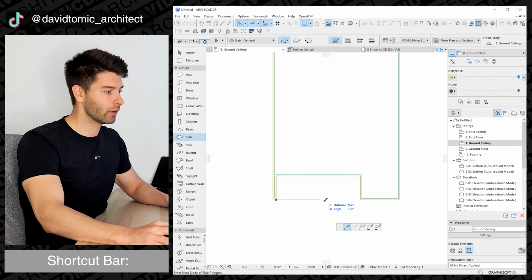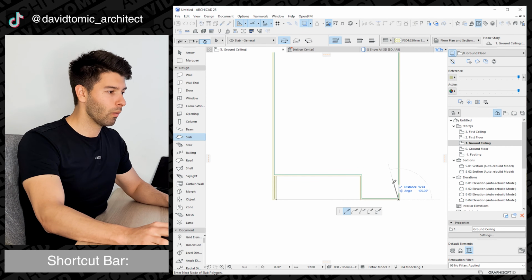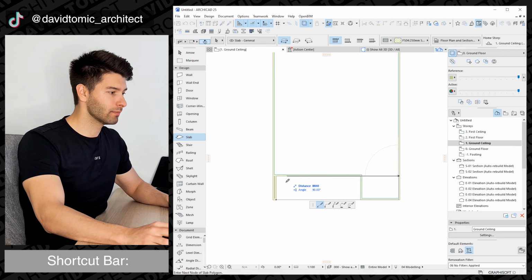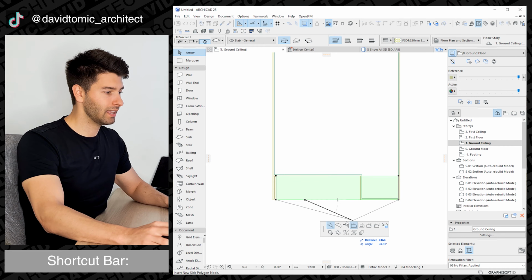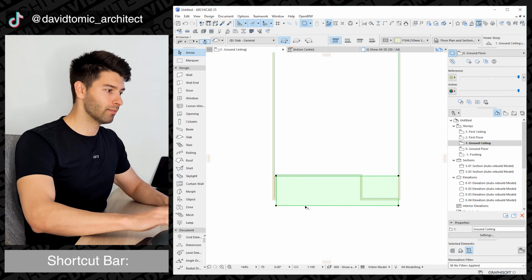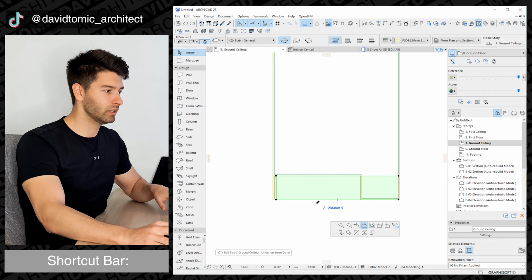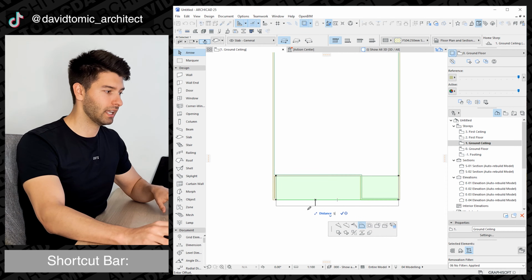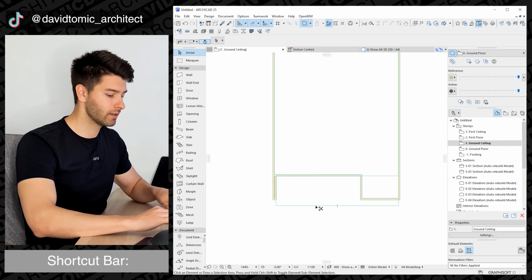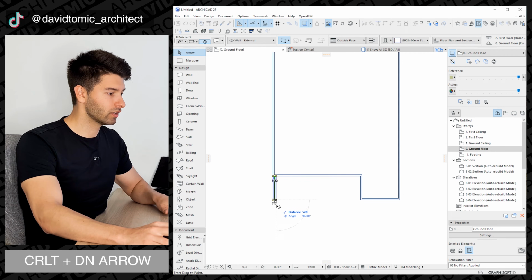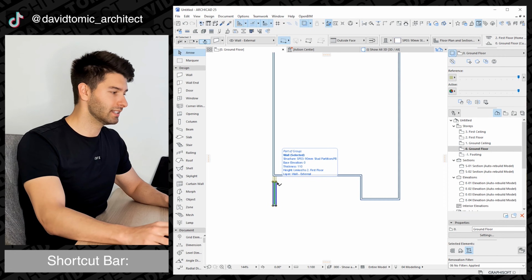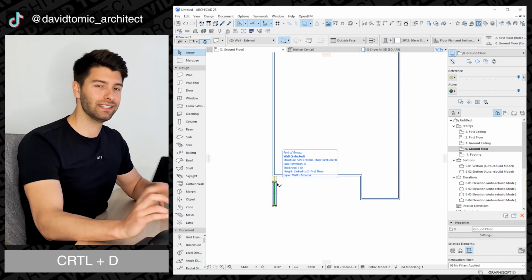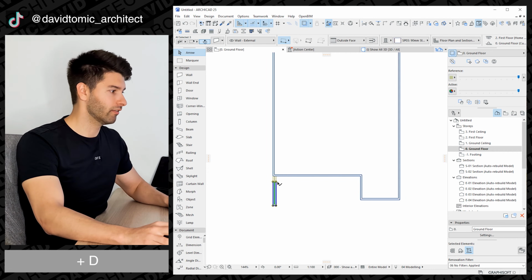Now I'm going to copy this slab across, and instead of stopping in front of the wall, I'm actually going to come all the way out in this instance to create some sort of balcony here and then drop back down. I do want to extend that about 500 millimeters past as well. So the same way as we did it in 3D, click on that line, offset edge, start typing in 500, and then Command down. I'm also going to bring this back out another 500 by simply following the same steps we did before, which was Command D and then pressing the D button to type in 500.